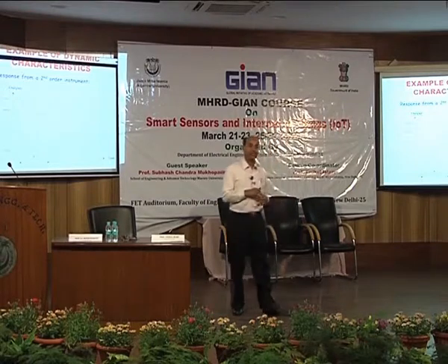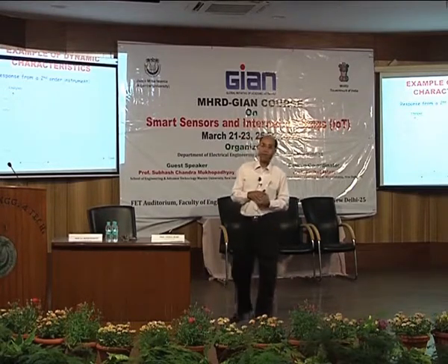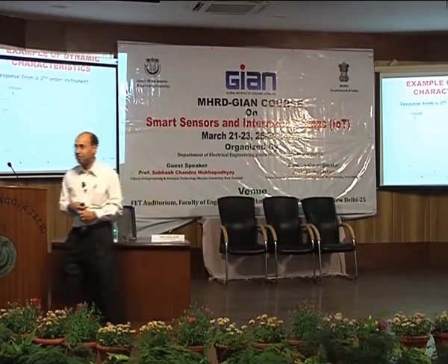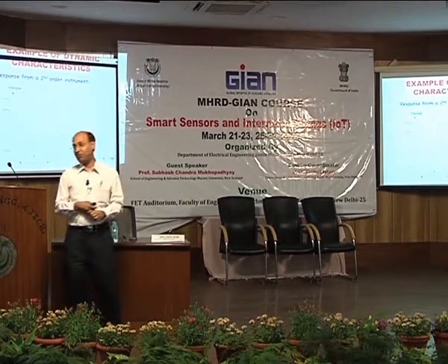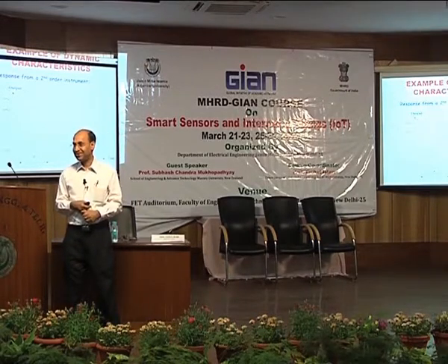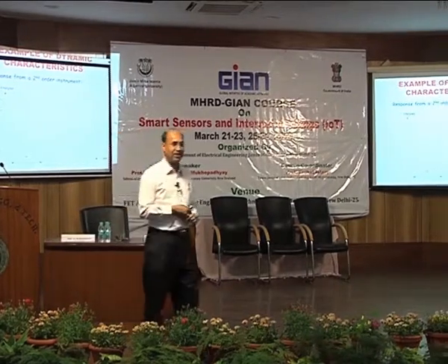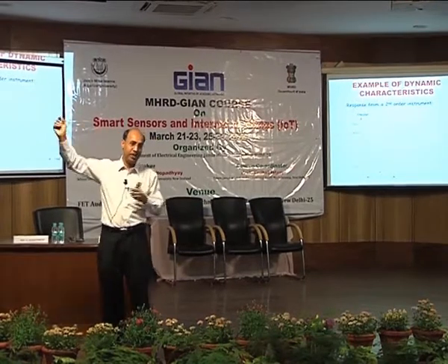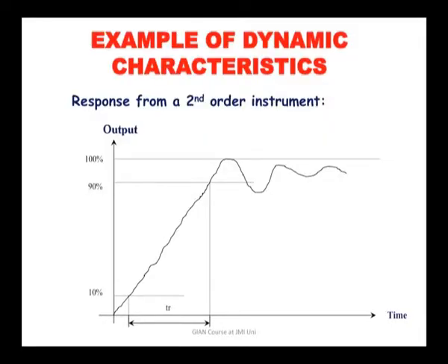For the second order system, again, what type of damping have you got? Okay, there are three types of damping, and if you are unlucky, you may end up with underdamped. So you have a second order equation, s squared plus 2 delta omega n s plus omega n squared. That delta is very, very important. If the delta is less than 1, you are underdamped and you will be oscillating. But if you can make delta either 1 or higher, then you can bring the system to behave as a first order.